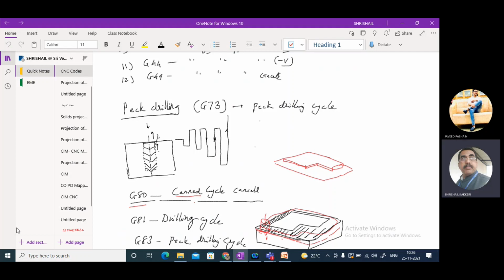You understand? So the threading is one canned cycle. That particular canned cycle, you are going to give the type of profile and how much depth is required, and it will be performing the threading operation. A canned cycle is a particular repetitive cycle meant for this particular purpose only. Maybe it is a threading operation, maybe it is a drilling operation, or grooving operation, whatever it is. It is a standard. Okay. If you want to do a grooving also, grooving cannot be done at one time. Slowly we have to remove the material. Correct, no?